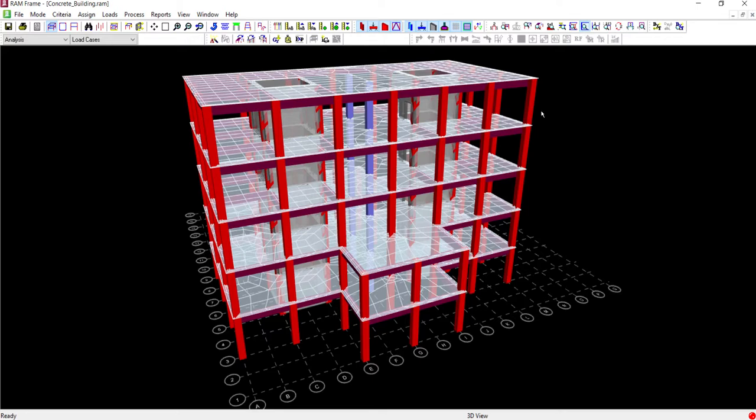As I mentioned, the program considered it meshed with the plate elements. But if it is rigid, then all the plate elements should be considered to be bounded by a single rigid diaphragm. Here it is a semi-rigid diaphragm, so it basically behaves as plate elements which can undergo some out-of-plane bending and all. It can also undergo in-plane deformation as per the definition of the semi-rigid diaphragm. So basically, this one is capturing the true nature of the structural response if you have any kind of cutouts, or if you want to consider some in-plane deformation of the physical plates.